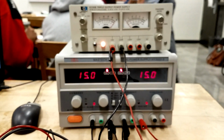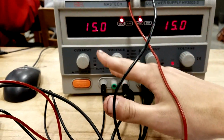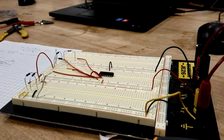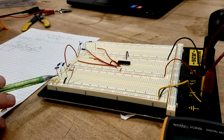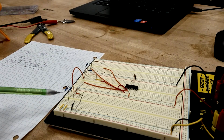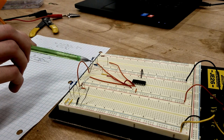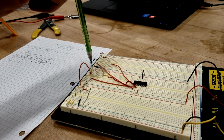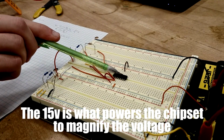What we actually have here is two power supplies. Up here we have a 7 volt power supply, and down here we have a -15 and a +15, which is hooked up corresponding to our circuit. So we have our 7 volts coming in through here, and this is going to be our V2. Peels off and feeds into the positive pin. And then this is our original 1K ohm resistor, which goes off into a separate 2K and 1K. This is going to be our V2. And we have a positive 15 volts powering the chip and a negative 15 volts going on.